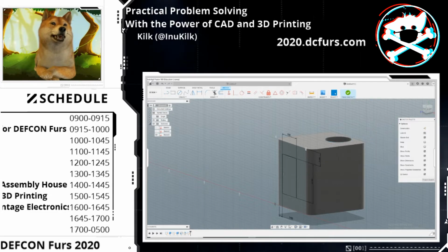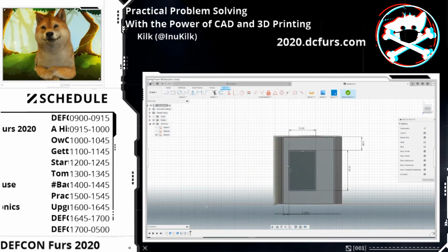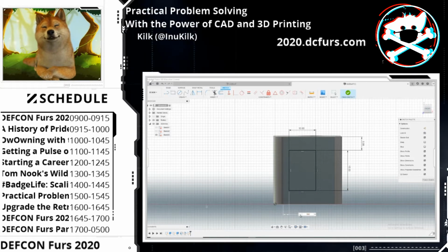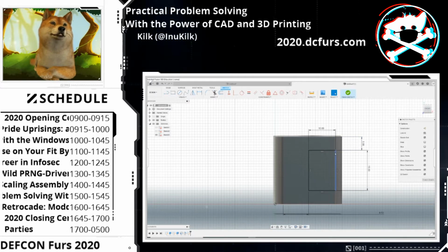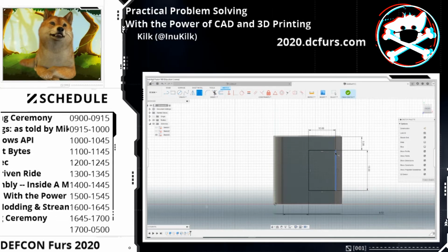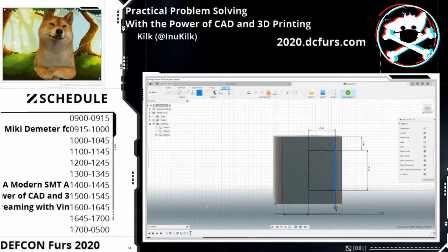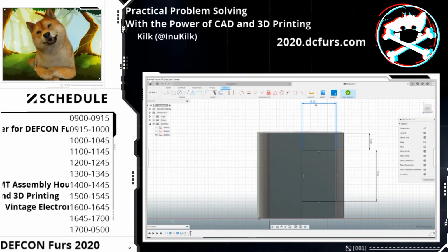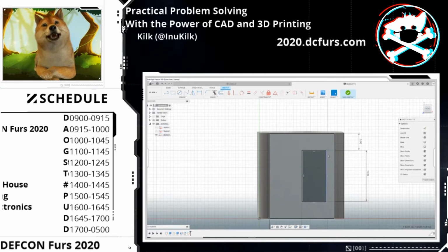So that's cool. So we know this is 19, right? This top edge. How about we dimension this by doing 19 divided by 2, right? So now it's going to put it in the center, in the middle. Now see, now it's overstretching because it's not constrained to this. We can do here, and let's just make it. Oh, this is going to be a problem. So sometimes you don't want to constrain that. You can delete that, and so now you can freely move it again because there's no constraint.